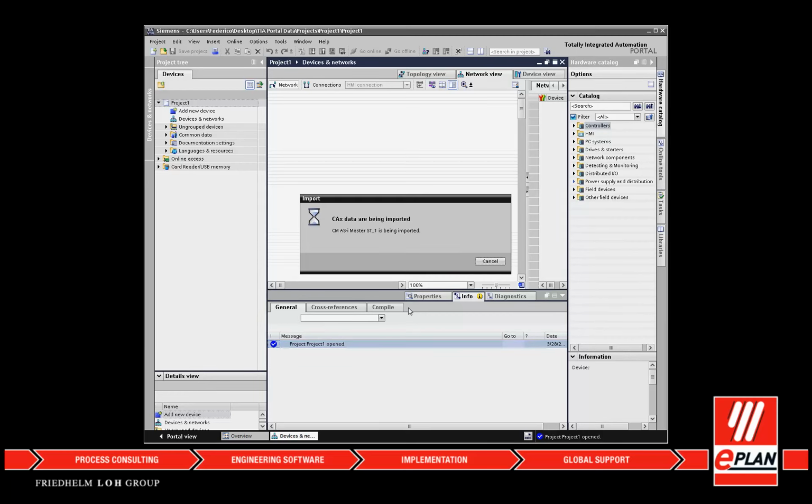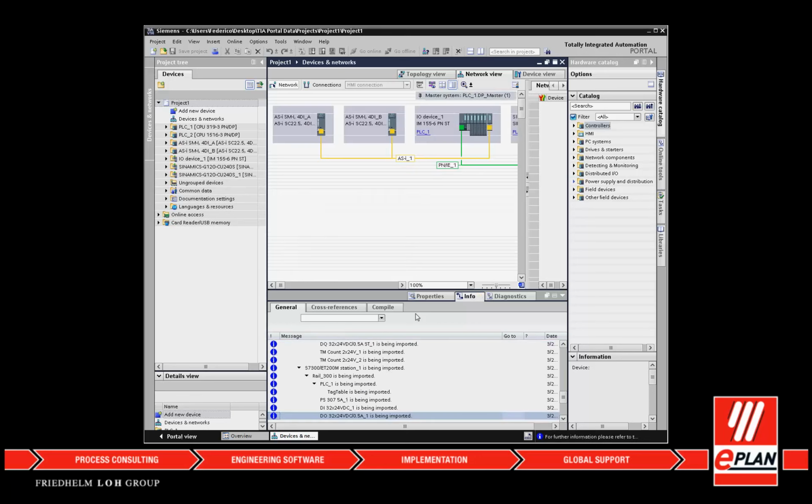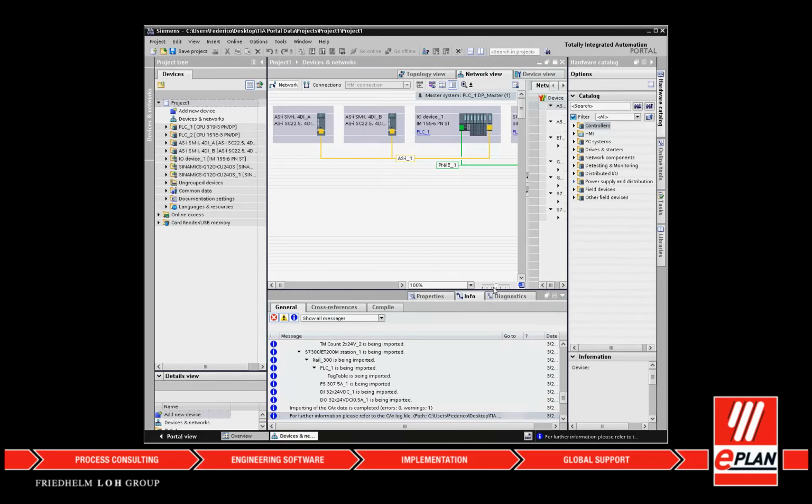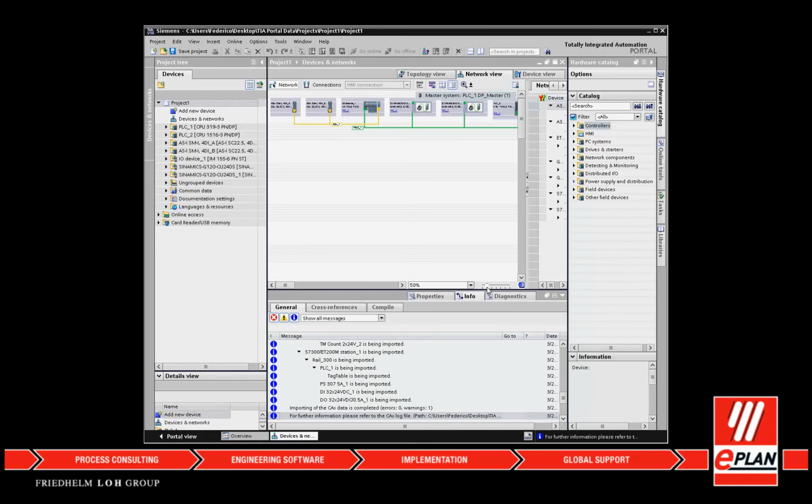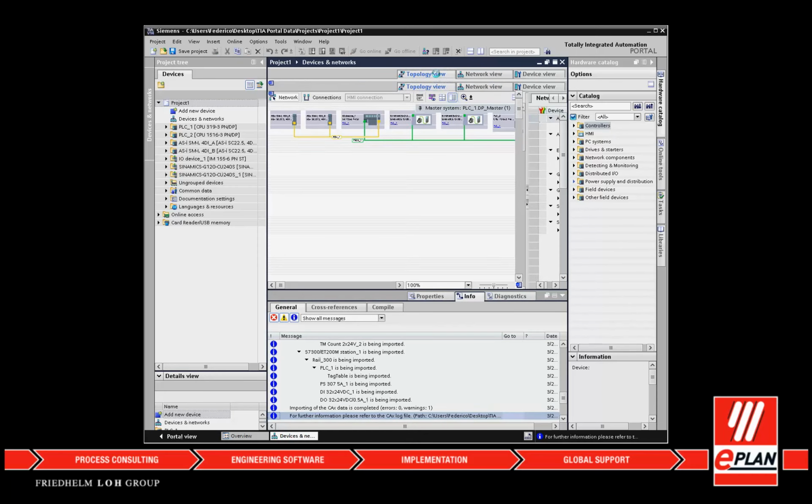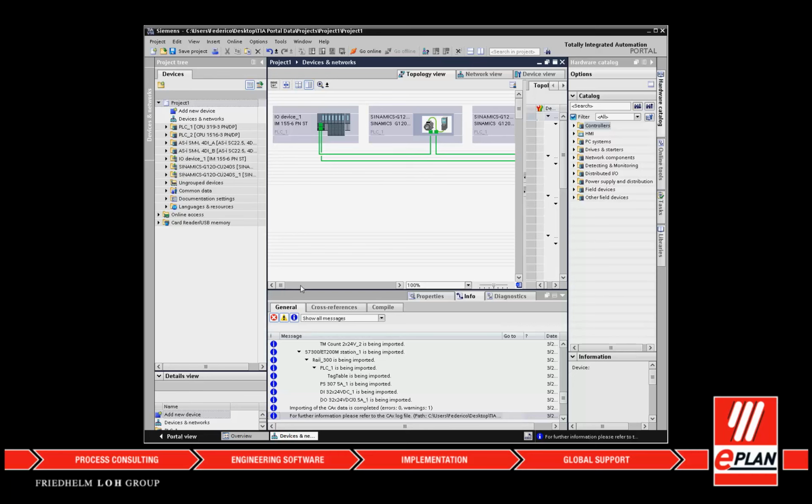In principle, the following configuration data are exchanged. Hardware data of the used devices. Symbol table contains the assignment of the symbolic address to a hardware address. Network structures, logical view, meaning that only the relationship of the devices is described. With EPLAN Electric P8 from version 2.7 onwards, it is possible to exchange data via AutomationML to Siemens TIA Portal and back again.